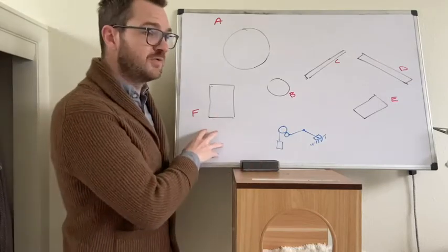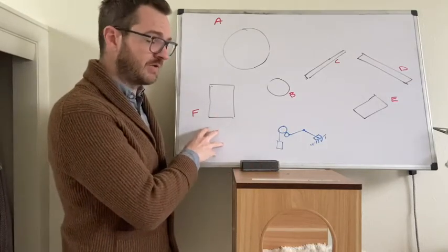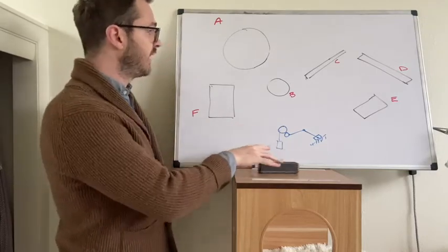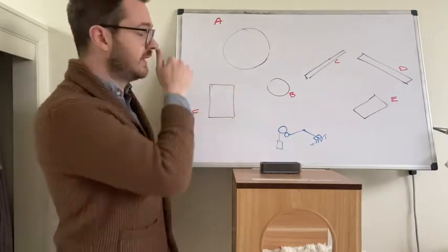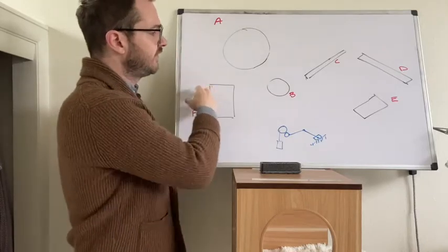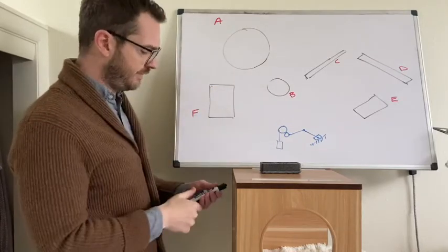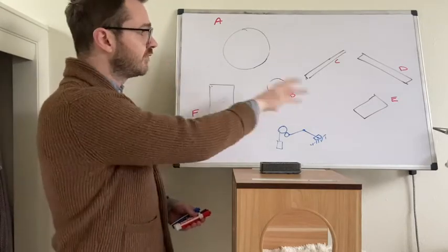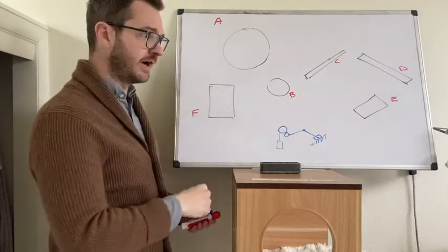If we're going to do sum of forces and moments, we have to do free body diagrams. Remember, this diagram is not a free body diagram. Free body diagram means all of the parts exploded. So here then are the 6 bodies, A, B, C, D, E, F. Before we do the equations, let's go through and put all the forces on these diagrams.